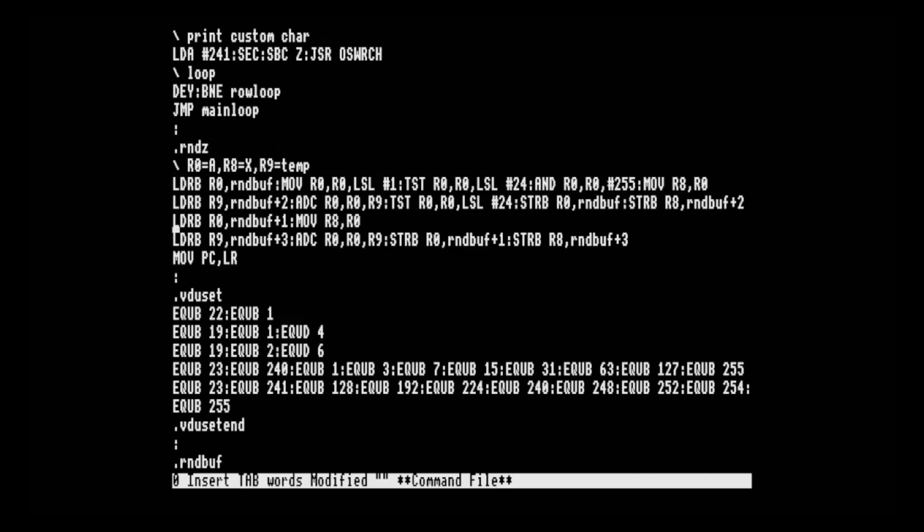Now the reason they did that is because quite often you call a subroutine and you don't want to call another subroutine beyond it, so this avoids you having to write out to memory and read back in from memory the return address. It makes calling a subroutine a lot quicker. Obviously, if I wanted to call another subroutine from this one, I would have to store the link register somewhere so it's not lost and I can return back to the right place.